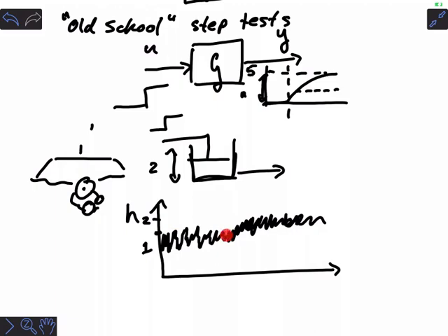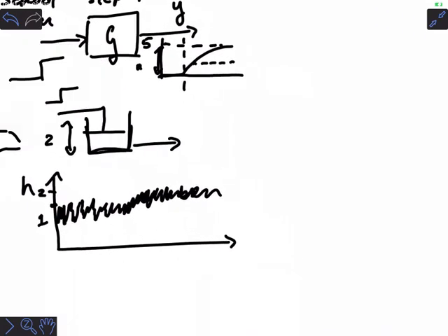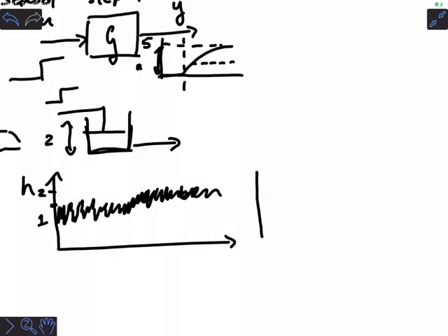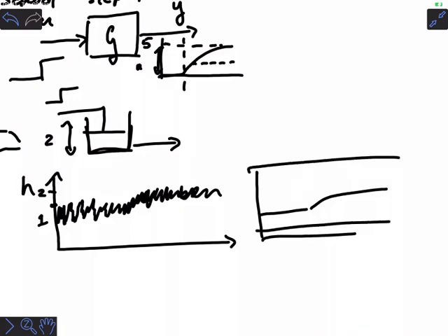So if this is not true, if instead I can make a small change and measure a nice step response, and I can clearly distinguish it, and I'm far away from any kind of safety bounds on that system, a step test may be a perfectly reasonable thing to do. Of course, you'd still be annoying people because they probably were operating here for a reason.